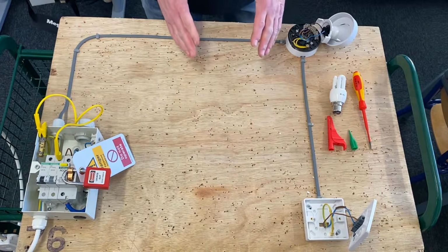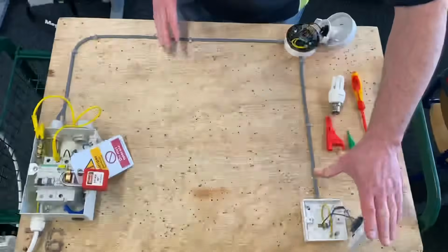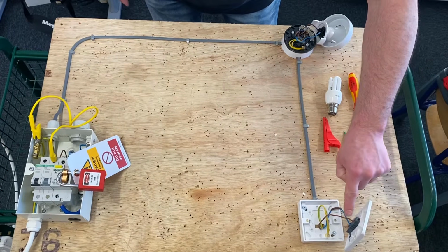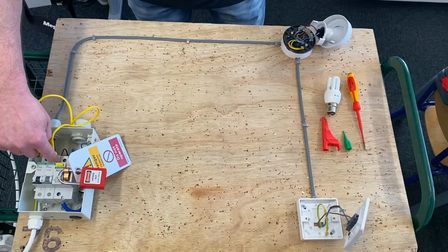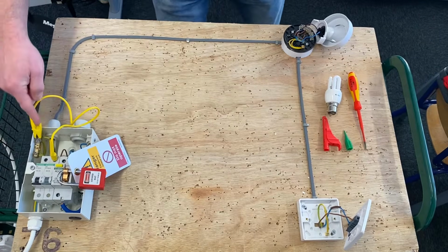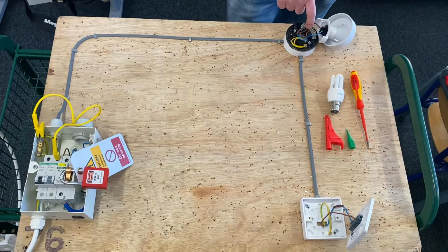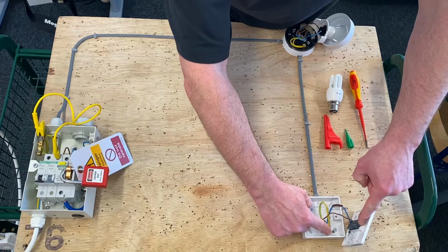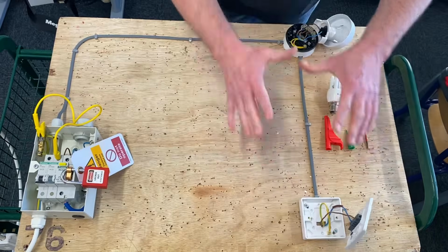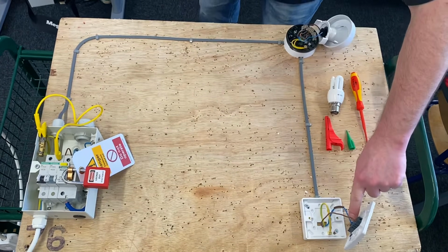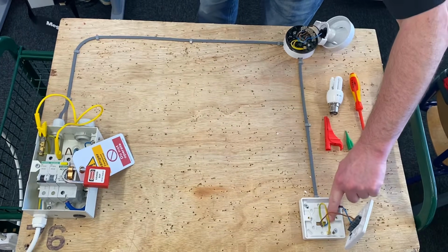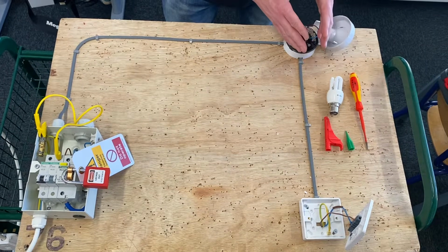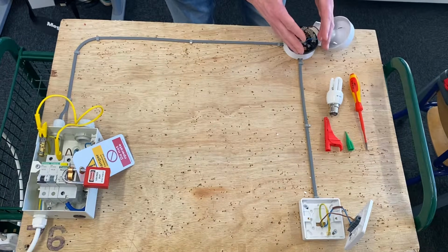When we were measuring the CPC and line connection in the switch down here, we had the line conductor from here. So the line conductor came from the consumer unit. It came into the loop terminal and down to that position there. And we measured between the common and our CPC connection. So when we did the lighting point, we actually had an additional piece of cable being our switching line conductor back, which meant the resistance was higher at the lighting point because more cable was in circuit than it was at the switch.